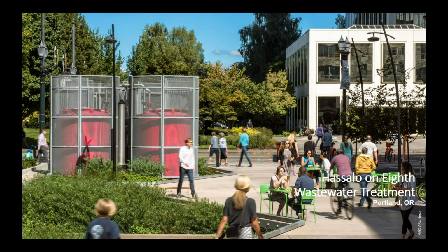As engineers, one of the most important principles is health and safety of the community, and so we're often communicating early on with a client and stakeholders about how we're managing health and safety. So the water in the treatment system is always below surface. We're scrubbing any potential odors that come from the system. We're making sure we're limiting access to critical components. And so that's very much a conversation that happens a lot in early stages of our concept and design development.